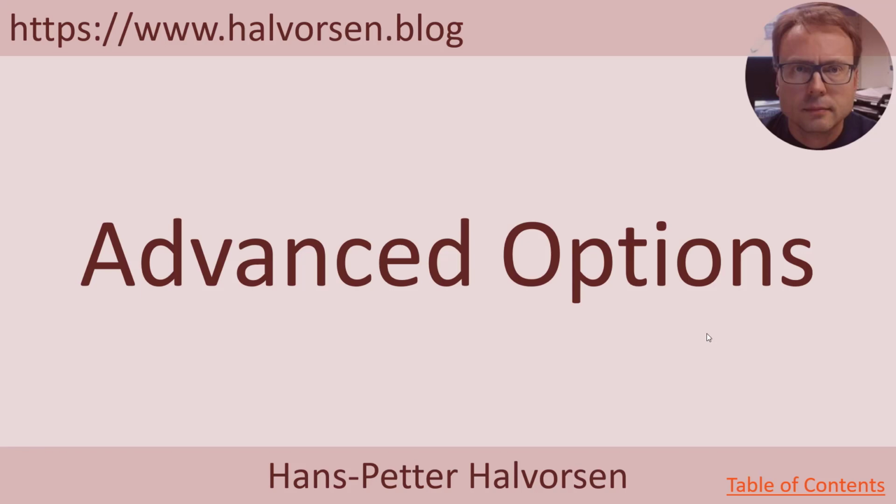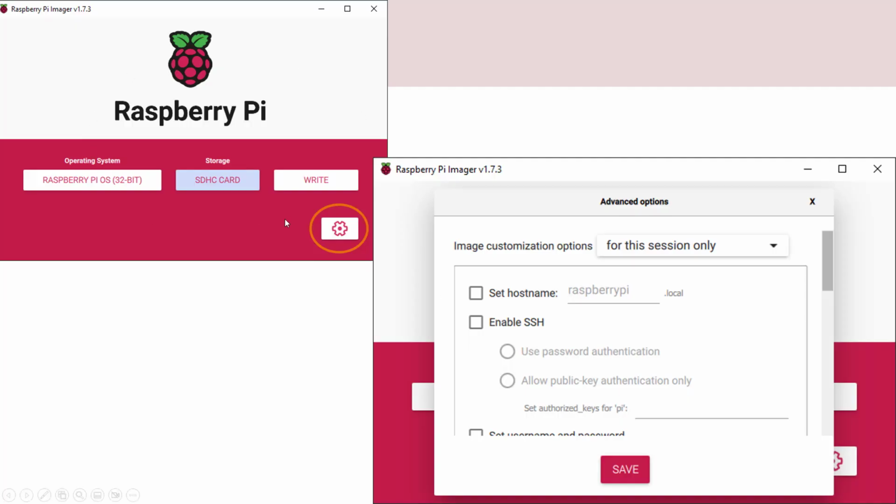But in this tutorial we want to control the Raspberry Pi remotely from our computer, so we will choose and use the advanced options in this Raspberry Pi imager. If you open the Raspberry Pi imager and select this configuration icon, these advanced options will pop up, and here you can specify and enable SSH, you can specify Wi-Fi network, etc.